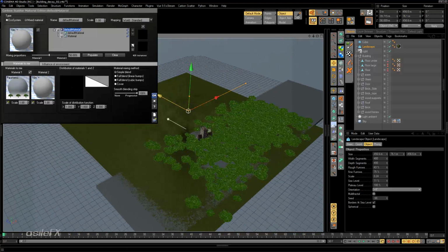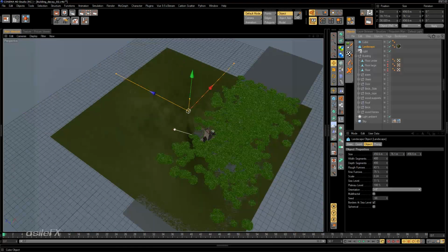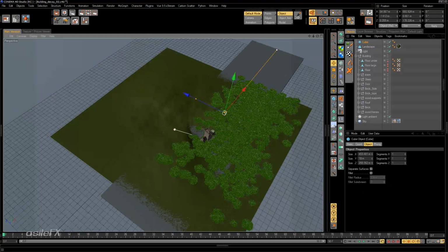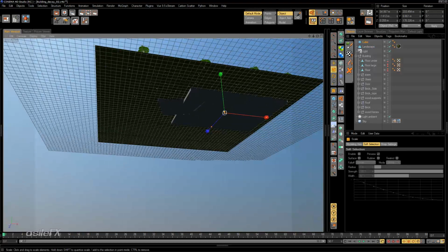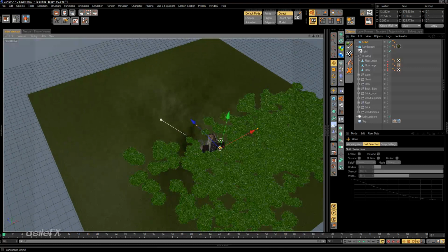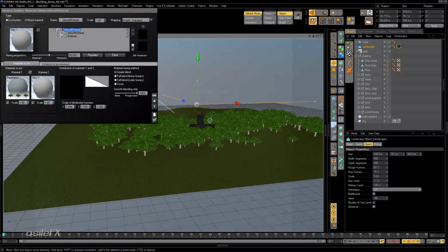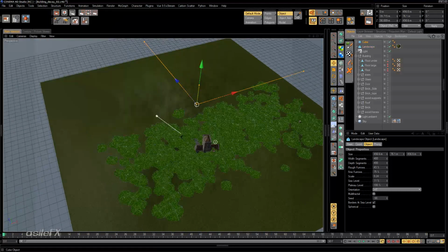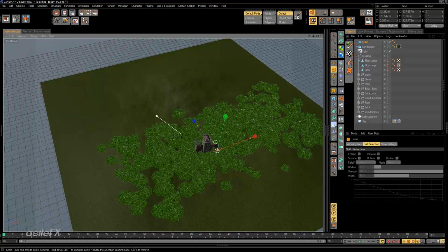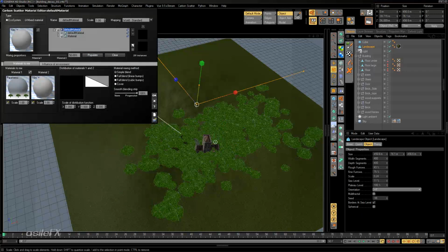So this is also a useful method for creating LOD zones. And what you can do is we'll just take this current ecosystem and make this our high-res area. So go to the landscape and populate. And it looks like maybe that scale on the model mode is not refreshing entirely. That looks a little better.